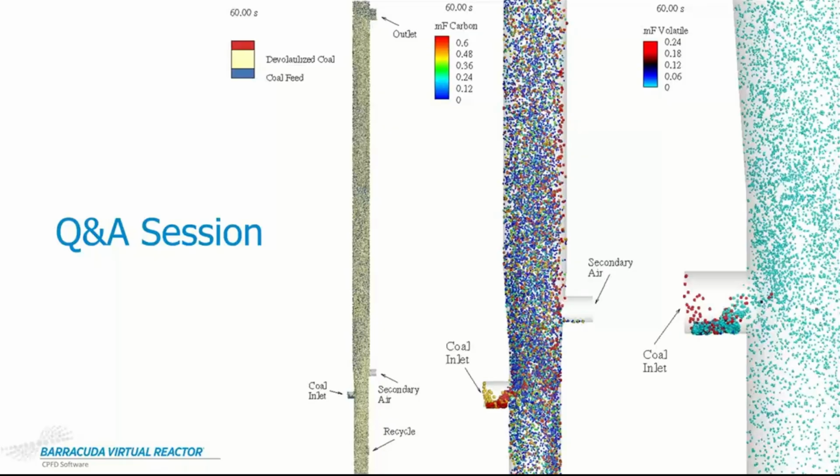All you have to do is make sure the boundary conditions are defined on the faces that you want them defined on, and that the dimensions and everything are accounted for in terms of where you're placing. If you have any post-processing planes and things like that, make sure all of that is taken care of. But absolutely, you can remove the existing geometry in the setup, bring in your own geometry, and continue running that model.